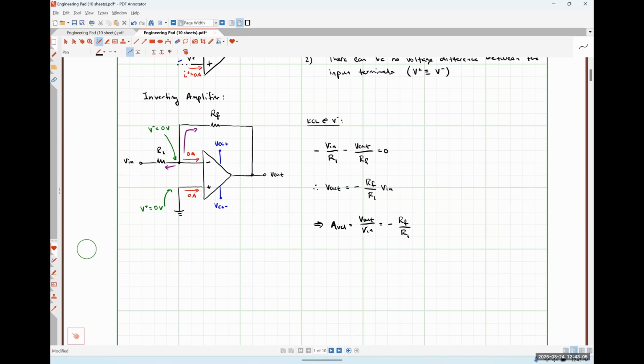We can definitely use an inverting amplifier like this to boost the level of a DC signal, but that is the most boring application that we could have for a negative feedback op amp, just bumping up DC signals. That is possible. It's just there are other ways to do it. I'm not saying that they're necessarily better ways, but op amps, particularly negative feedback op amps, are used for what's called analog signal processing. That is literally what they were designed to do.